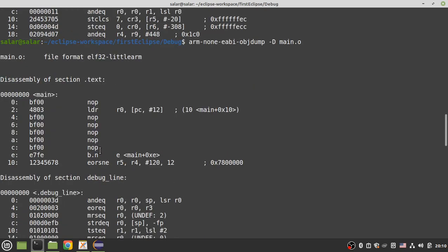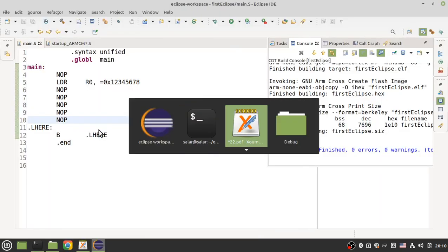the text section. Another time, here is my code, but this time PC address is 2, offset is 12, and the address of your constant number in your flash memory, the relative address, is 10. Here is a hexadecimal number, okay. Let's solve the equation for these values.